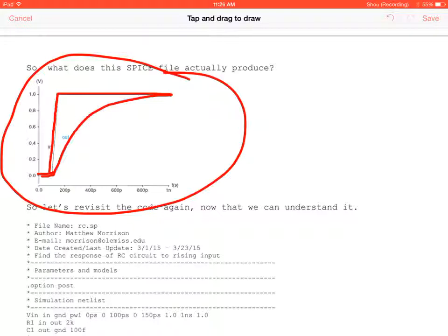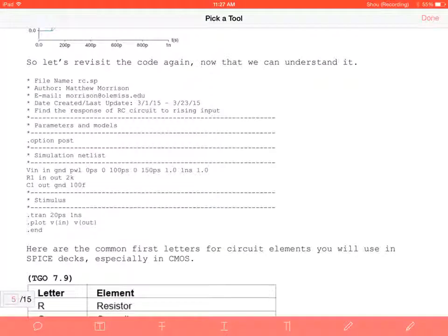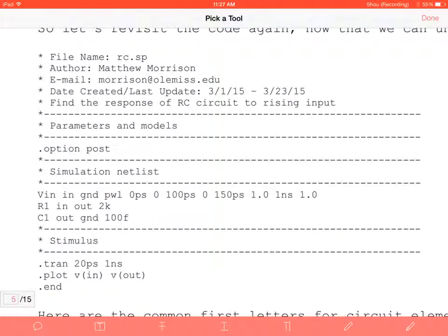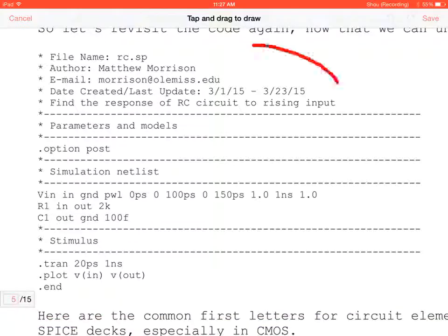So what's happening here is you have written a .tran where it's measured at every 20 picoseconds for this 1 nanosecond, right? You've written this input voltage, you've designed the RC such that it is properly configured and will properly compile and the circuit is together, and then here we have now written this segment of SPICE code. Have your input, write .post, first thing you do after .post is write .end. If it has a star, it's a comment.